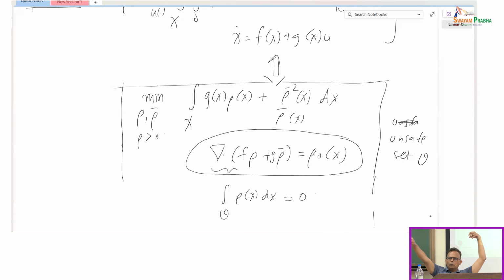You want to take the robot from an initial point to a target point while avoiding the unsafe set. What you construct are these navigation functions or the barrier functions. So what are navigation functions? Navigation functions are sort of like an attracting-repulsion potential kind of function. Whenever you have the obstacle set, you create a repulsion. The functions take a very large value and repel the robot from getting closer to that, right?